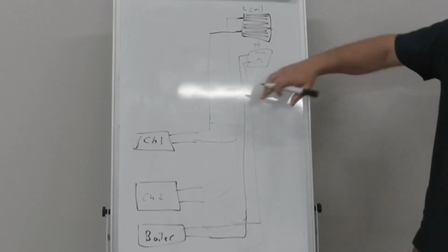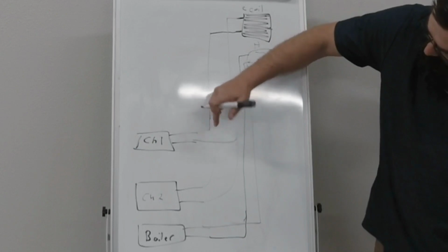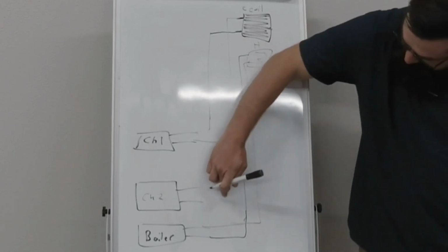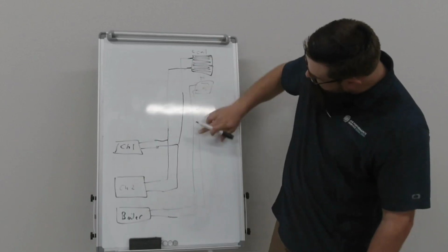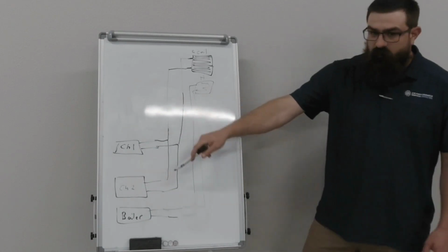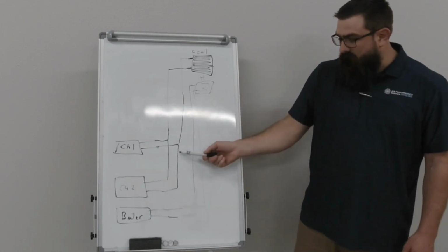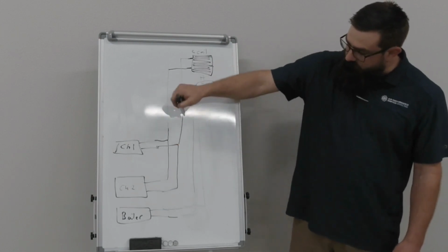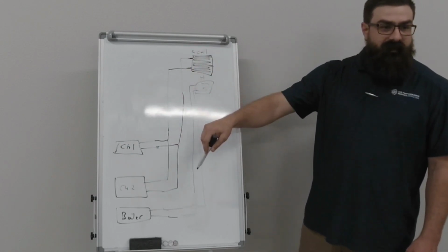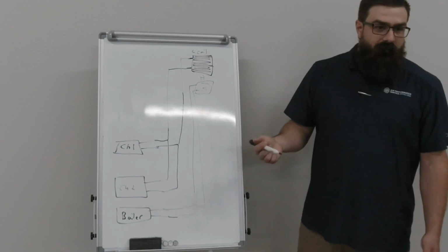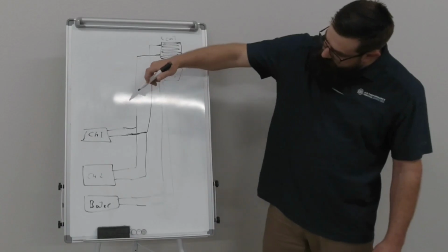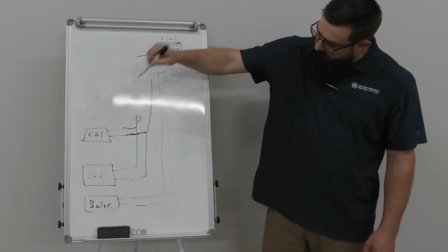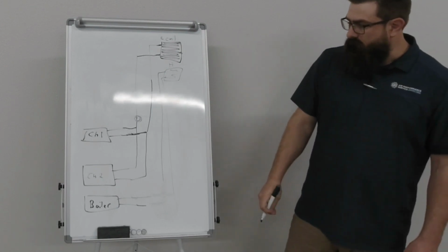Where things get confusing is when we go to what we call common header or dedicated, and all the different kinds of pump architecture. This is what's referred to as a common header. Both pieces of equipment are sharing the header that goes to the building. So each one can pump into that system at the same time, equally, independently, whatever it may be. They can both pump into there. And the pump in that scenario is gonna be right there just above where those, yeah, it's gonna be right in that location. One central pump or multiple pumps, all feeding the same line.